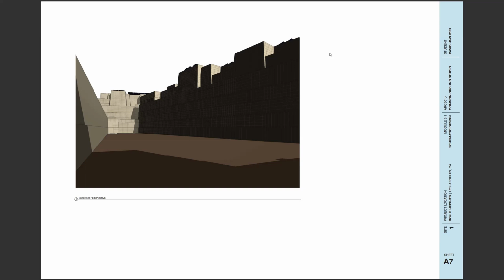There's also a debate with modeling in Revit if it should be done using a curtain wall or with a standard wall. So I'm currently working through that as well. But for these massing stages, I am using a specific stacked wall with 6-foot increments. And it's turning out very nice, especially in 3D views. There's a lot of character to it.